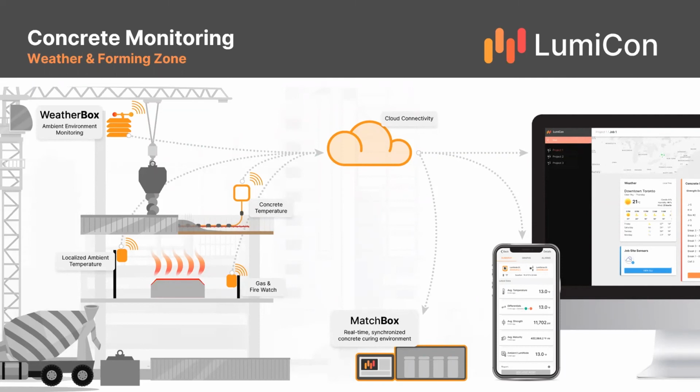So having a weather box, having a weather station that can help monitor the temperature, ambient temperature, humidity, wind, smoke, these are all important, first for the safe operation at the job site, and second of all, the local ambient temperature and relative humidity or precipitation all affect the curing of our concrete.